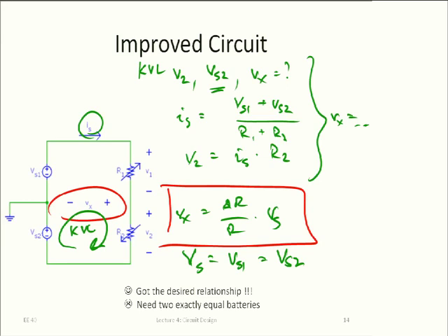So the positive side of VS2 is connected to ground, right? Is that true with VS2? It's like positive side and negative side connected to each other for the second voltage. Yes, so if, for example, they would be both 3 volts, then if we make this ground, you have plus 3 volts up here, and you will have minus 3 volts down here. Right? And the total voltage across here would be 6 volts.